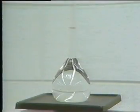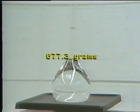To calculate the bulk-specific gravity of the fine aggregate, we also need to know the weight of the flask filled to its calibration capacity with water at 73.4 degrees Fahrenheit plus or minus 3 degrees. The weight of our flask filled with water is 677.3 grams.